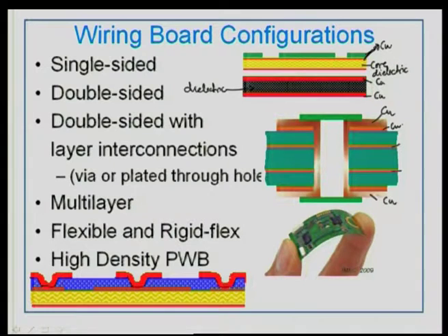So, you have layers like 1, 2, 3 and 4 layers of copper, and this is the plated through hole. Where is the plating done? The plating is done here. This is the plated, and this is the start. This one is the starting copper.